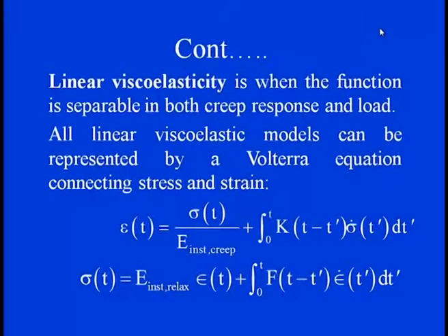So, we can say that linear viscoelasticity is nothing but a function that is separable in both creep response and the loading conditions, and all linear viscoelastic models can now be represented by the Volterra equations, which straightaway connect the stress and strain along with this propagation.